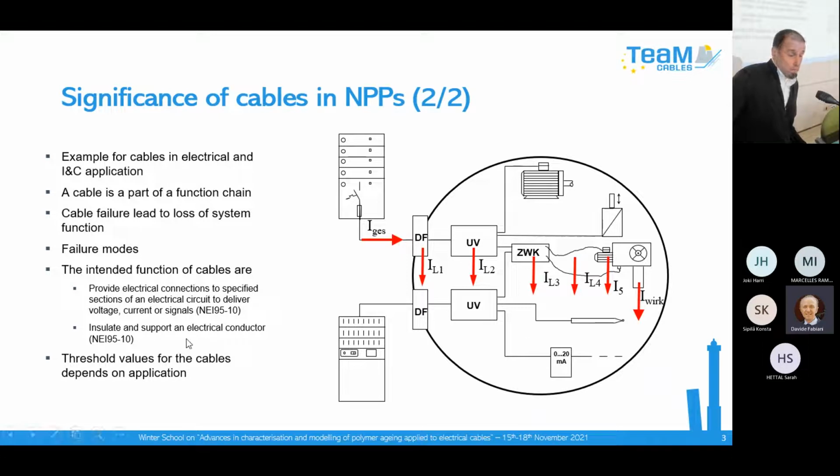And the second intended safety function of a cable, according to American guidelines, is the transmission of current. But this is not really subject to aging. Here we talk about metal, and our experience shows that it is not subject to aging. So we have the focus on the core insulation of the cables.